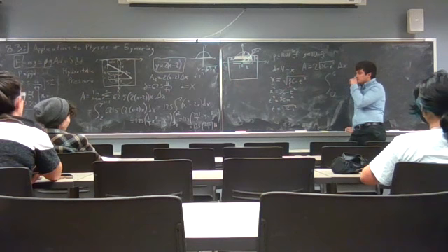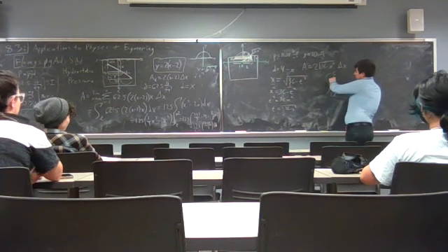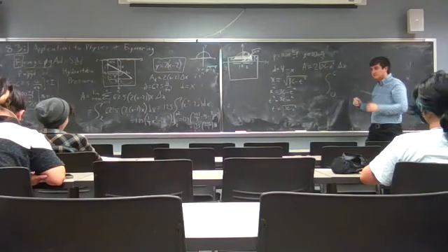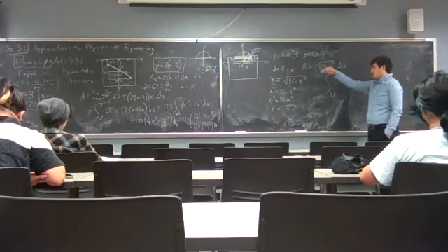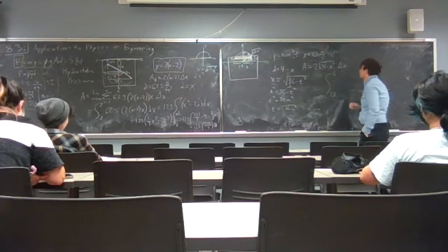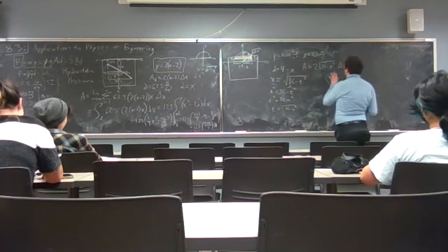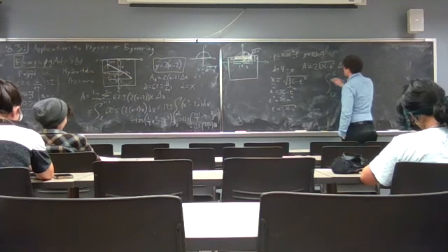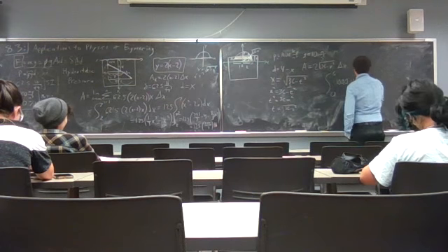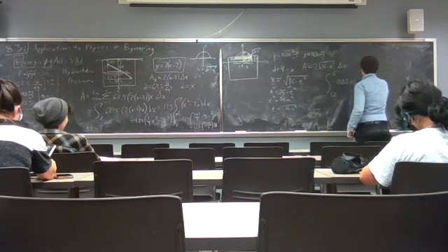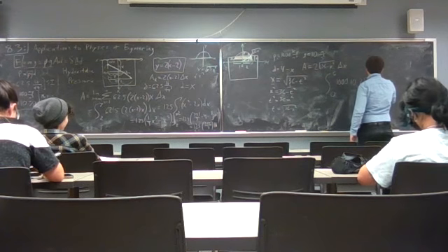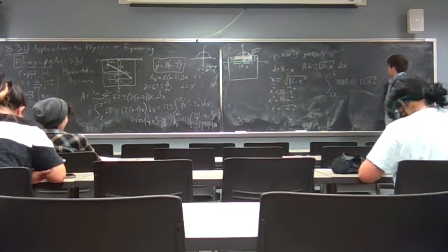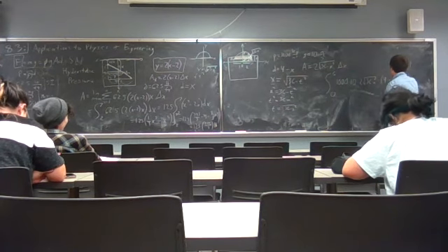You would only get a little bit of it because you still need to factor in, notice when I go to 6, I'm going to have like a negative portion that's going to kind of cancel it out, kind of like a little bit of a Boole effect of some sort. But you need to take all of it into consideration. So, okay, 0 to 6, and we're going to have 1,000, right? Because that's my density times 10 times the area, which is 2 times the square root of 36 minus x squared, and then times 6 minus x.